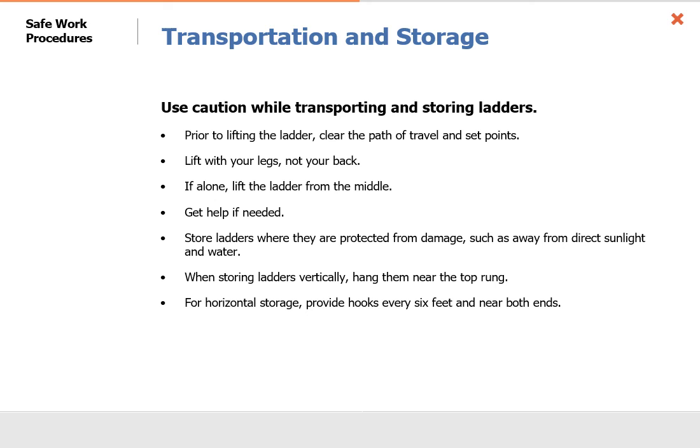Using caution while transporting and storing ladders. Prior to lifting the ladder, clear the path of travel and set points. Lift with your legs, not your back. If alone, lift the ladder from the middle. Get help if needed. When storing ladders vertically, hang them near the top rung.